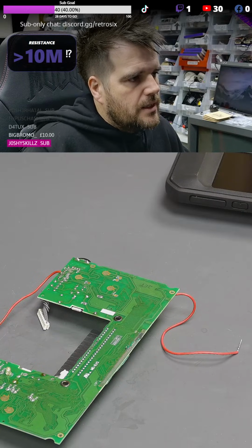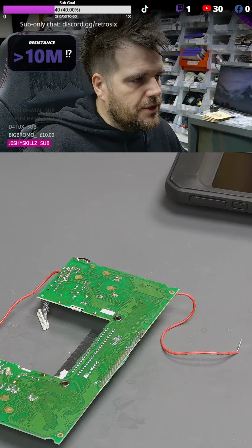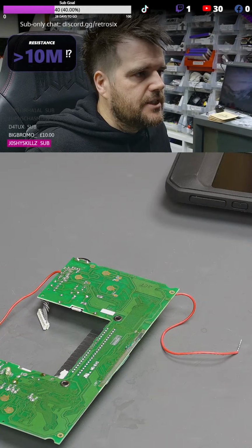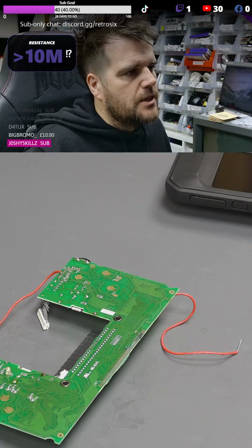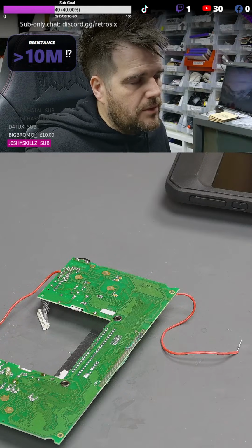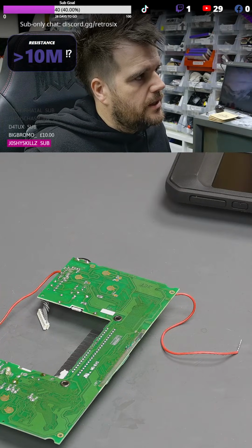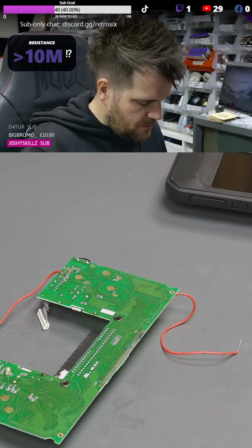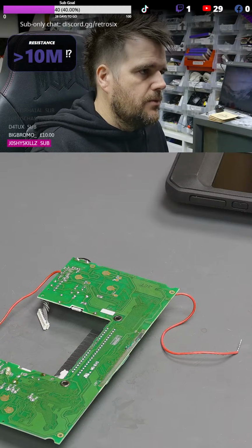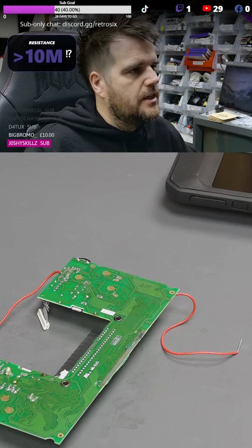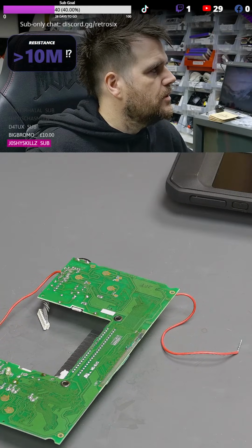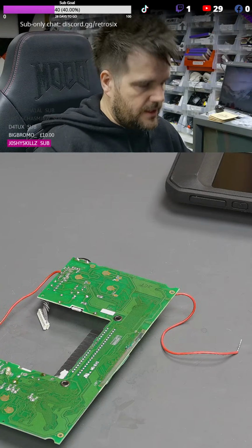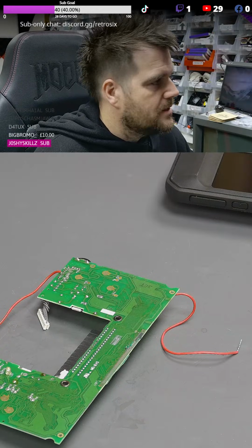Right, so what I'm going to do is update the software. 3 digits of accuracy is fine. If it's less than 5 ohms, you're talking about probably a dead short. So less than 5 ohms, we will do 0.000, so 3 digits of accuracy here. If I now kill that software, turn that off, compile this, we should be able to get that high accuracy.